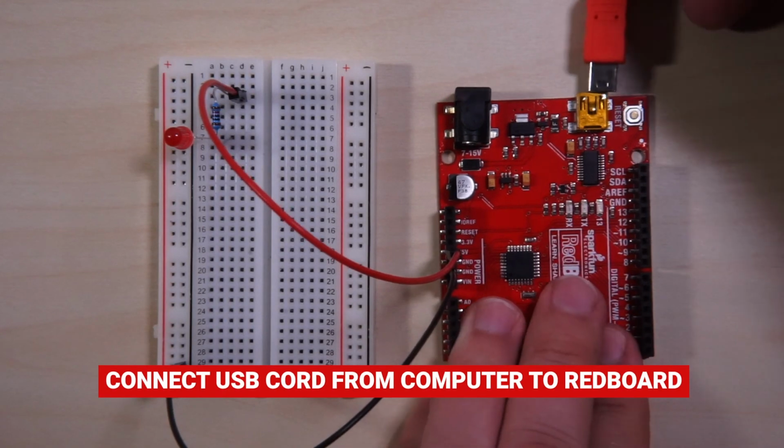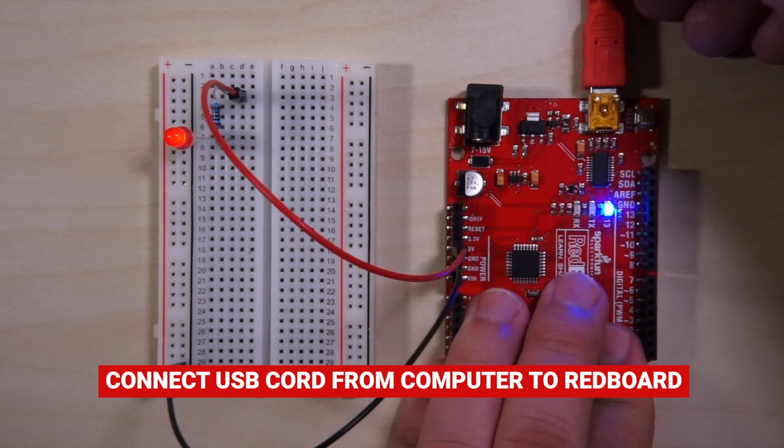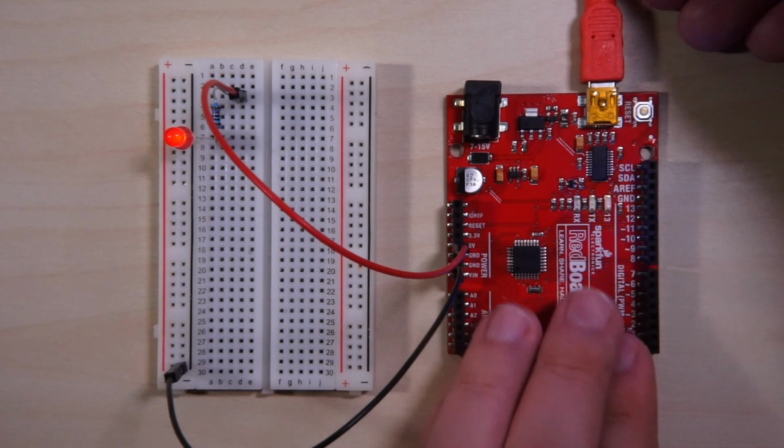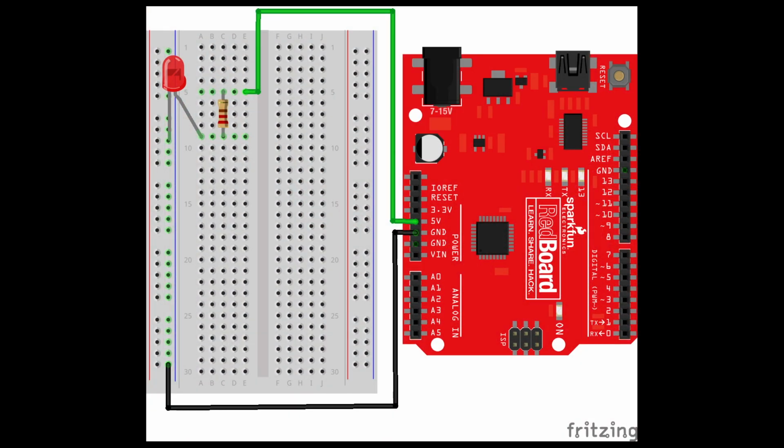At this point, connect your breadboard to your computer using the USB connector. If your LED is lit, congratulations, you've successfully completed a circuit. However, if your LED doesn't light up, don't worry. Recheck your connections again using the diagram from this video.